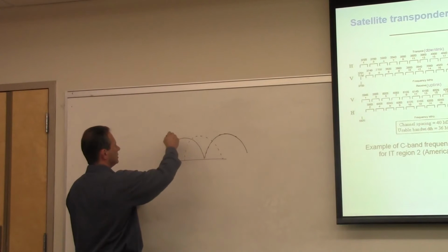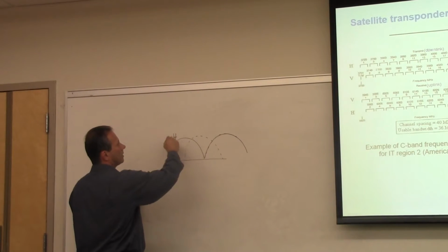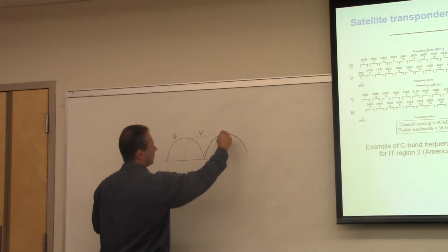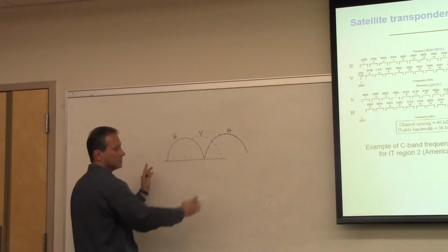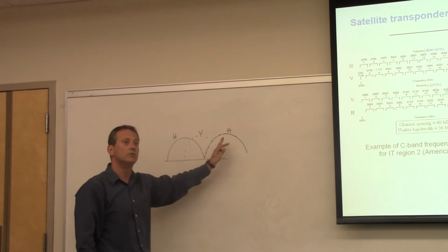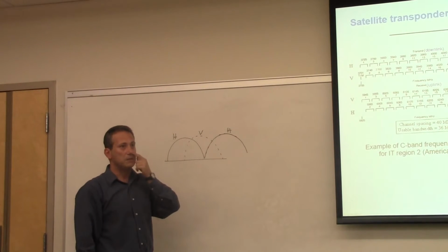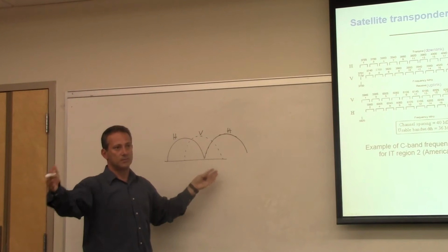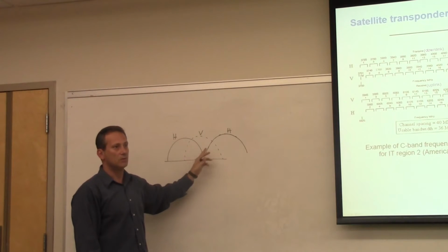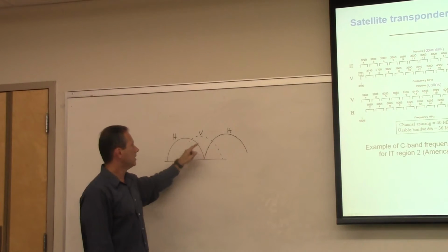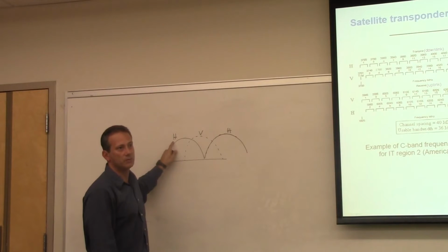Now you can see that their overlap is substantial, but what you don't see in this graph is, well, it indicates that these are horizontally polarized, and these are vertically polarized. So the ones that are horizontally polarized, on the same polarization, do not overlap, because here the only means of separating the channels is separating them in the frequency domain. V and H you can separate through polarization.